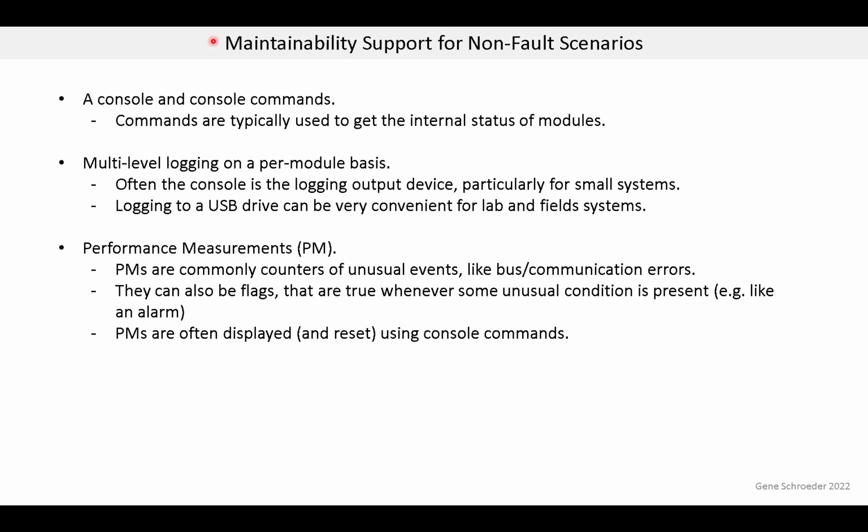So far, we've been discussing mainly fault scenarios. So I want to discuss maintainability support for non-fault scenarios for just a bit. These are techniques I used in my work and that I'm now using in my YouTube courses. First, it's key to have a console and console commands. That's your window into the system. And with today's MCUs, consoles have very low cost. Now, the console commands are typically used to get the internal status of the modules or to control logging.